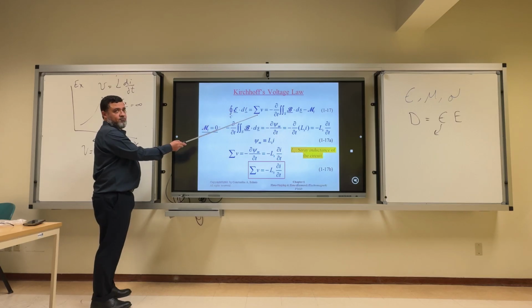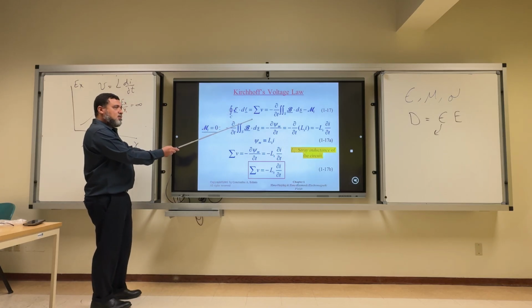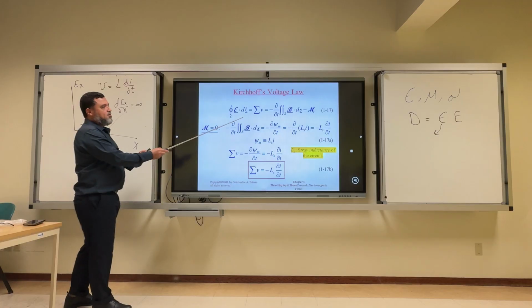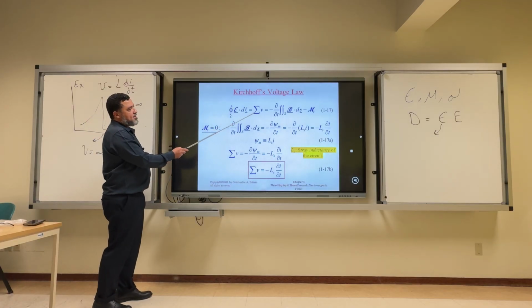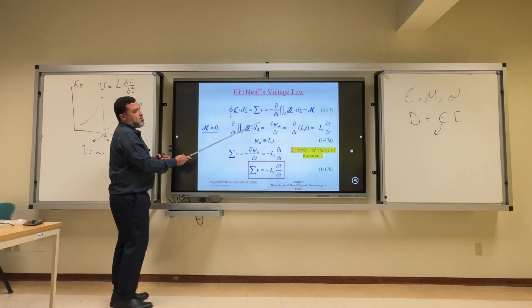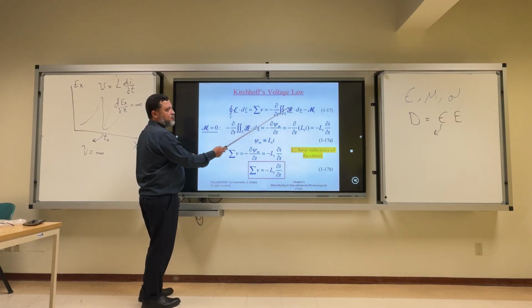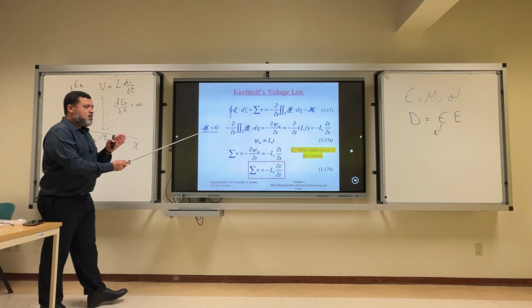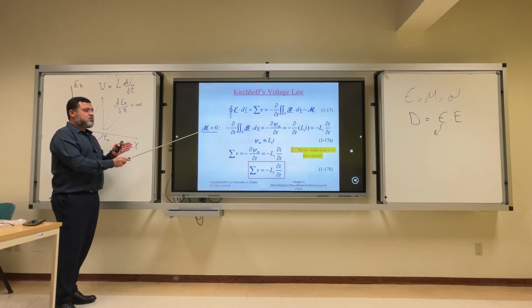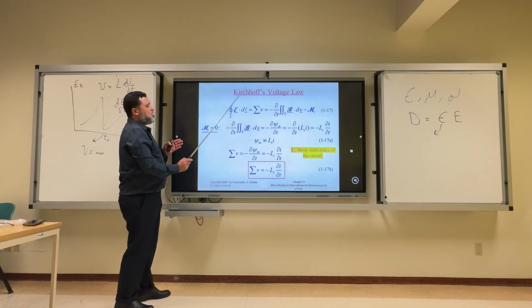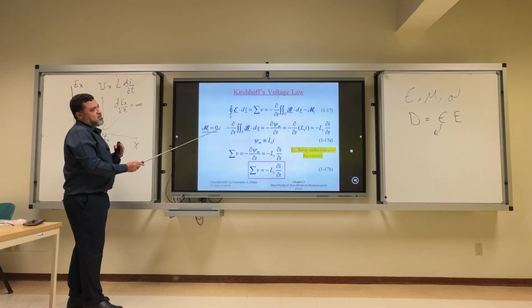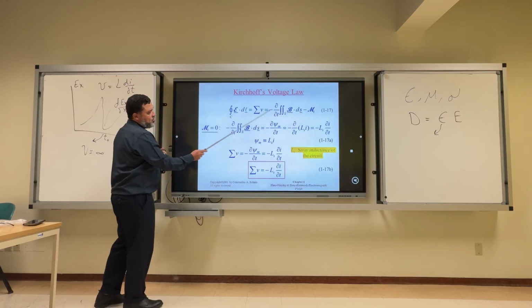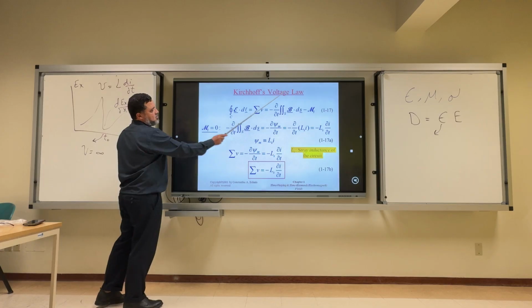E dot dl is an electric potential. So we can express this circulation as a summation of the voltages, assuming the voltage drop from positive to negative, and we need to take care of the polarity around this closed path. And this will equal the negative of the integration of B dot dS minus the embraced magnetic current. Assuming we don't have an embraced magnetic current source, we can cancel M_i. In this case, the unit of this is voltage, right? The unit of all of this.